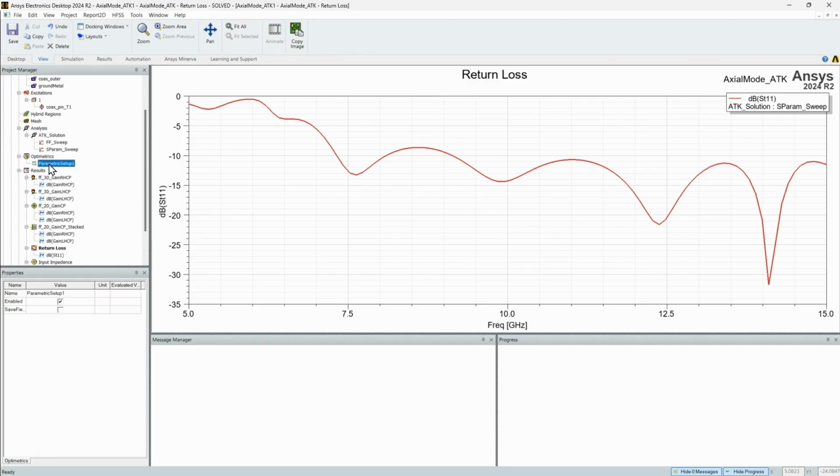And you can see we have our parametric value set 1. If you'd like, it's always good in case you have a few different parametric sweeps that you want to go through, it's good to just rename this. So I'm just going to rename this turns. You can do number of turns, probably better. However, turns will suffice for now.